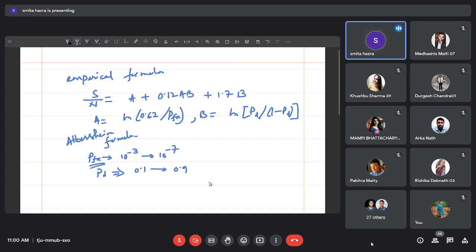That means to specify the problem with this PFA for the probability of detection, and if we consider the bandwidth is again 1 megahertz, then we can obtain the related S by N, and the S by N will give us a value of 14 to 15 dB, 14.9 to 15 dB.